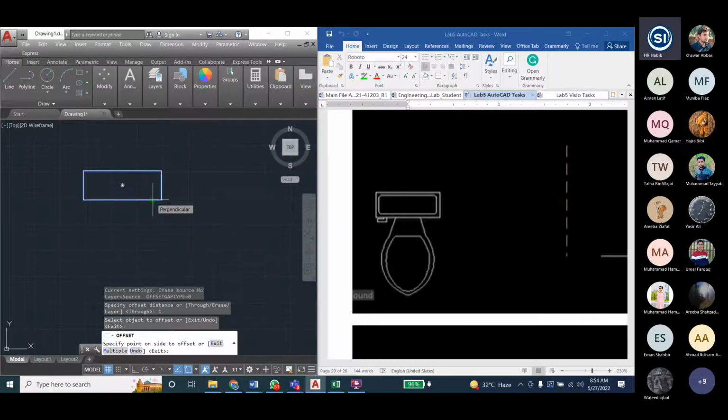Offset means, for example, if you want to place solar panels or anything else on a rooftop, then you cannot use the extreme edges of the roof. You have to spare some space on all four sides in order to move or walk freely, for cleaning purposes or something like that. You need some path to move or walk through. So that's why you need the offset. Offset is actually the distance from the original boundary at which you want to create another boundary. That is actually the offset.